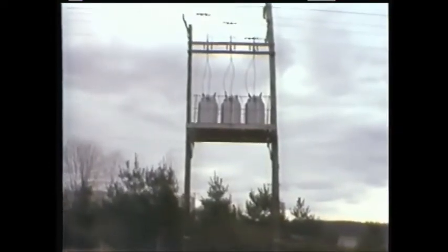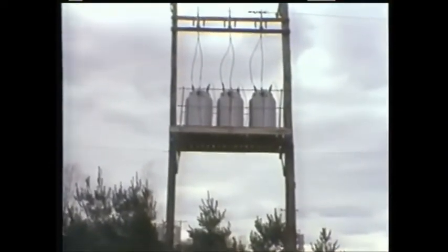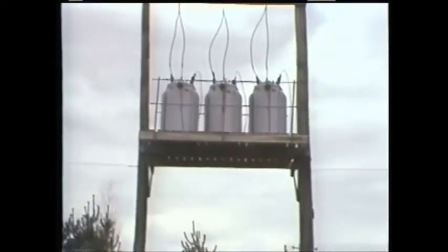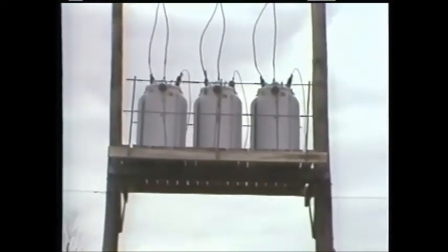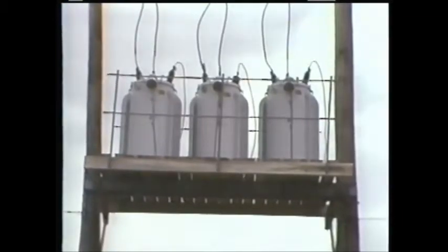Voltage regulators are an important part of a distribution system because they ensure that a customer will be supplied with electricity at a usable voltage. Voltage regulators and transformers are primarily used to affect the voltage in a distribution system. Capacitors are used to affect power. Multiplying the amount of voltage applied to an AC circuit by the amount of current flowing through the circuit gives you the amount of power in the circuit.